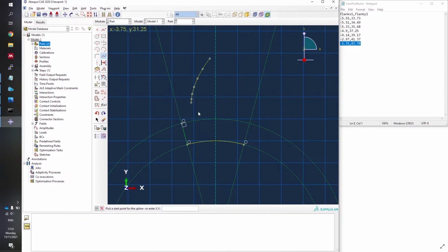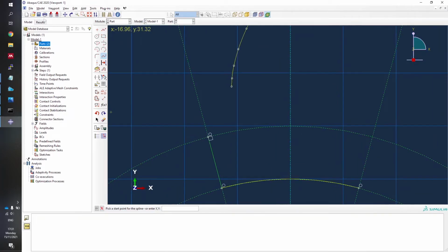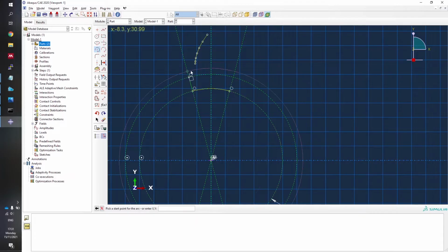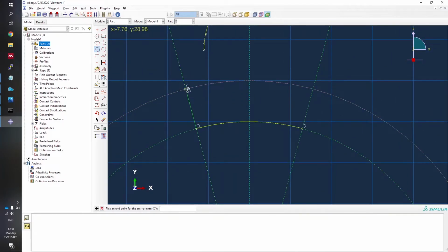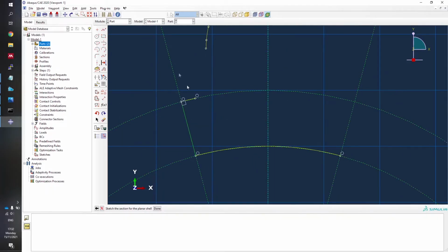The next thing we'll do is create the root fillet geometry, and I can expand this window again now. So I will create arc, center and endpoints, clicking at the origin, and then just create a small arc and make sure that it's not snapping to anything, but it is on the dedendum diameter. And then we'll press escape to stop putting arcs in place.